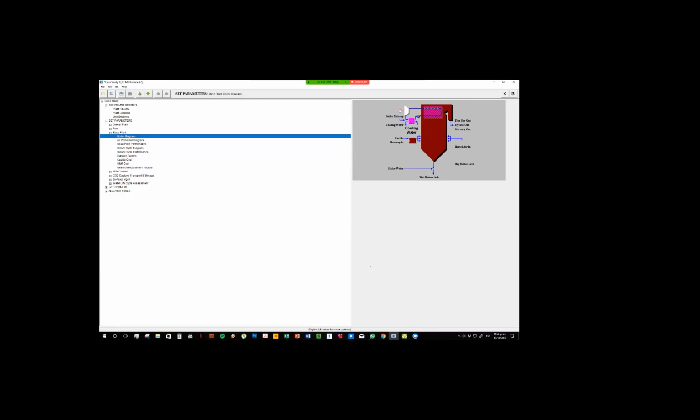And then the flue gas is going to go out with the mercury and the fly ash too, of course, right? In the bottom part, part of the ashes and the solids of the coal are going to go out with the wet bottom ash, because we're going to combine it with a little bit of water, right?